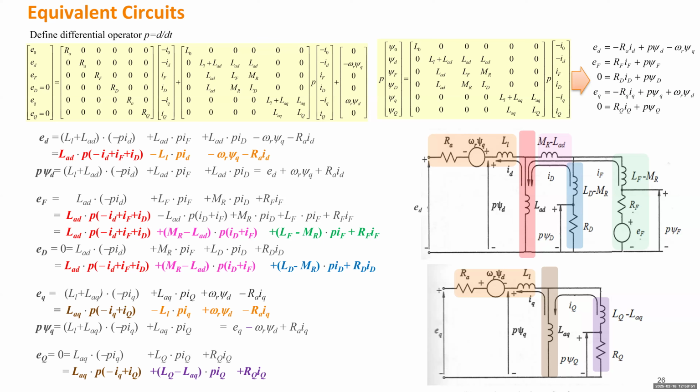Right now we have an even simpler model, giving us just two circuits, and it presents how the voltage is induced proportional to the speed of the rotor. This is considered the speed voltage of the generator. Another source is the DC source generating the magnetic field with the field winding, but that is not the major source of this generator.